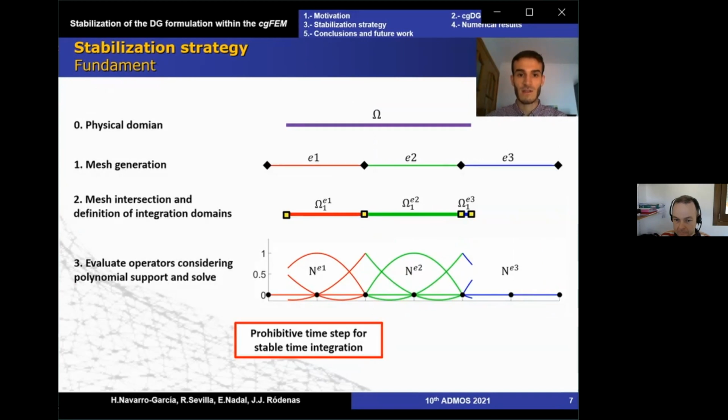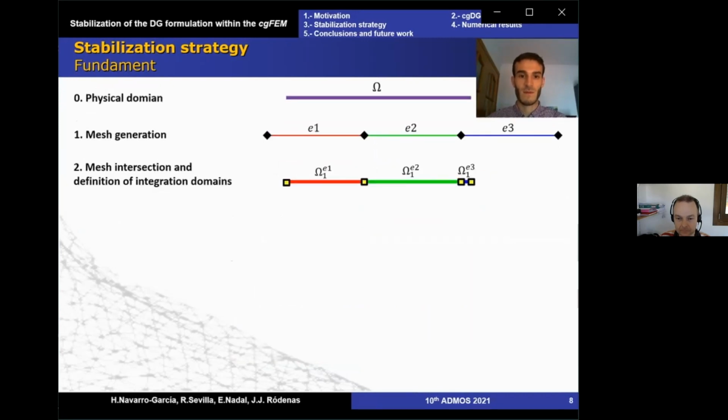In our case, this cut pattern also negatively affects the stability of the time-advanced algorithm. We propose a stabilization strategy that solves this limitation. It applies when the mesh geometry intersection has been computed. Using a geometry parameter such as the relative portion of the element in the computational domain, we can identify the element that may behave badly.